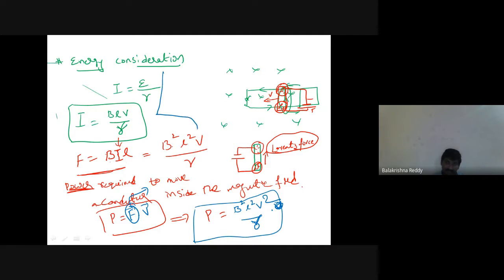Now power dissipation, just now whatever I spoke, comes due to the dissipation of energy in the form of heat. So that I'll write as PJ. Why PJ I'm writing is because of Joule's law of heating effect. We studied H is directly proportional to I square RT. Therefore, HJ equal to I square RT, where J equal to 1 we say. In the same manner, PJ equal to I square R we will write. R is the resistance of the conductor or wire which we have used in the loop.